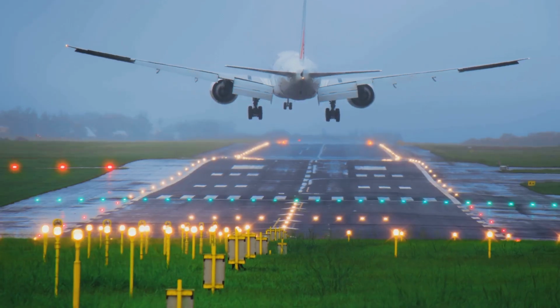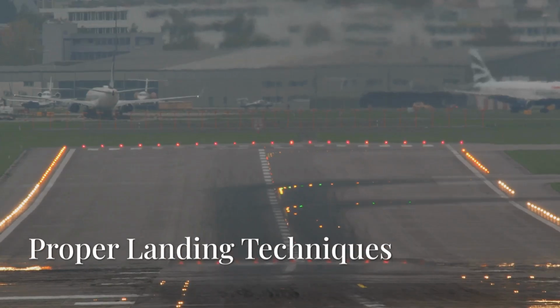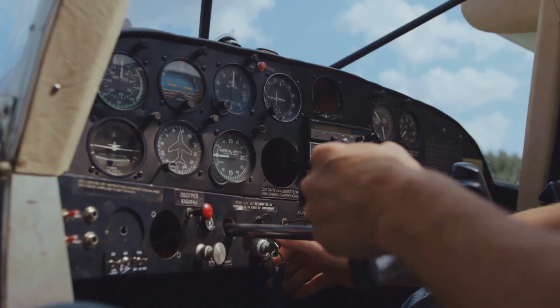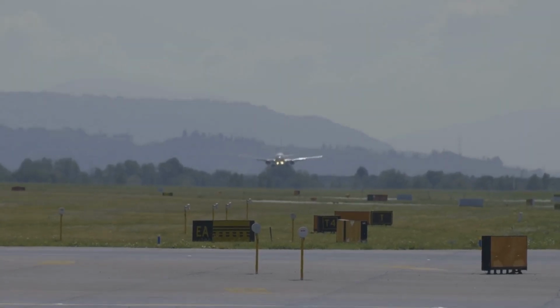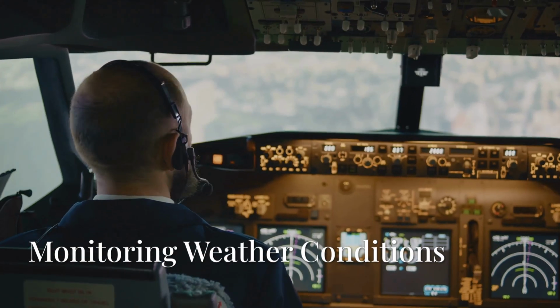How can we prevent and reduce the risks associated with hydroplaning? Proper landing techniques are absolutely essential. Pilots are trained to adjust their landing approach in wet conditions. This might include landing with a firmer impact, just to make sure there's proper contact with the runway.